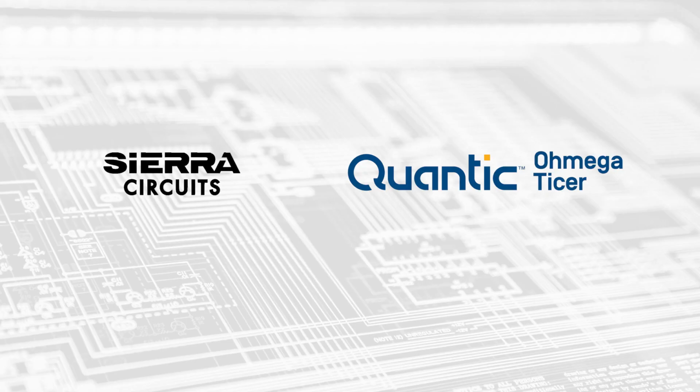When it comes to embedded capacitors, if your design doesn't have your power and grounds together, you may have to put in an additional dummy reference plane, a ground plane, because that's how it works very effectively. So we have seen some designs actually go from, let's say, a 12 layer to a 14 layer or something like that, to add that extra dummy plane in there. But because it's so thin, it doesn't add thickness. It just adds another layer or two in order to accomplish that.